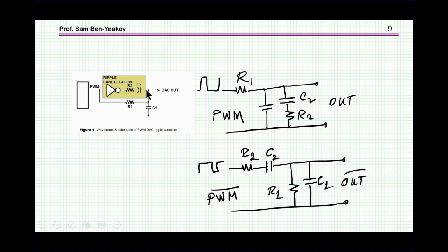It'll be distorted, and also you'll have a long rise time or setup time. So you'd like C2 to be very large. In fact, you'd like it to be infinitely large. But C2 is here, in fact, in parallel to C1. It's parallel to here.